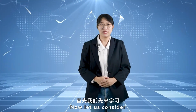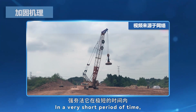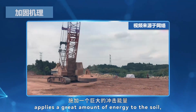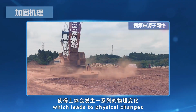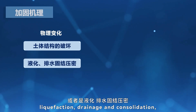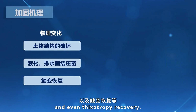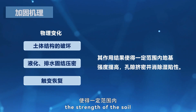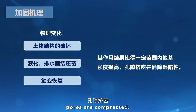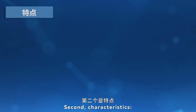Now, let us consider the mechanism and characteristics. In a very short period of time, dynamic consolidation applies a great amount of energy to the soil, which leads to physical changes such as the breakdown of soil structure, liquefaction, drainage and consolidation, and even thixotropy recovery. The final effect is that the strength of the soil within a certain range is improved, pores are compressed, and collapsibility is eliminated.